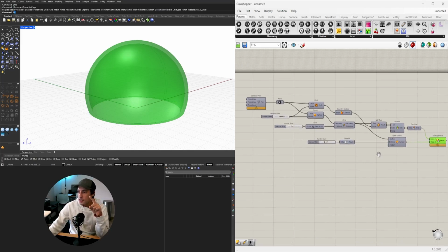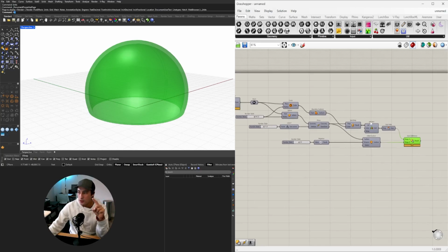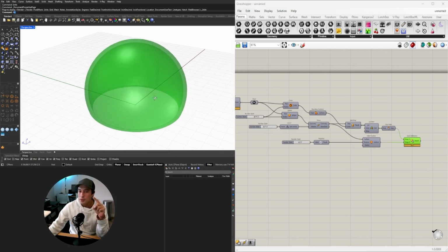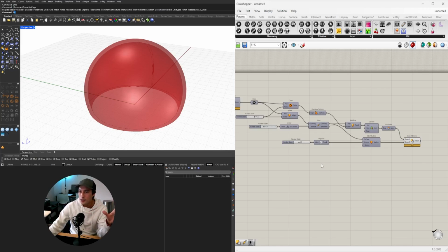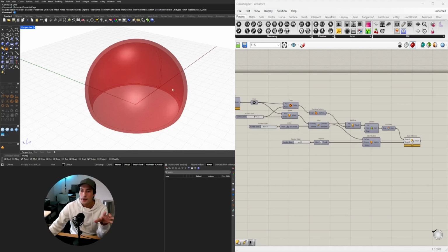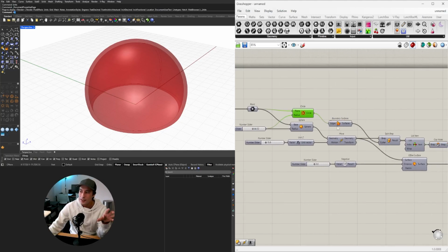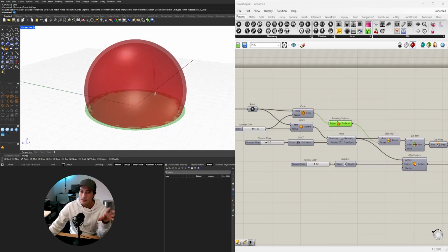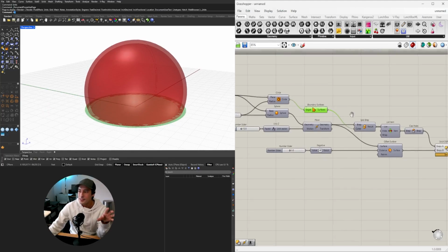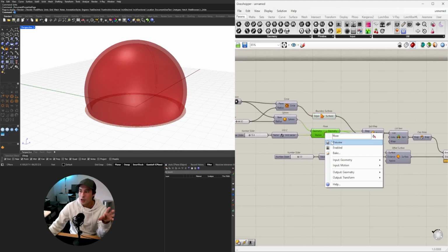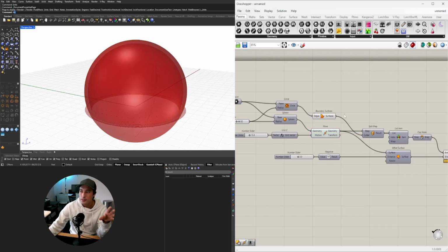All right, for this next part, for the door, we need to first figure out where the door is going to be located. And where the door is located, then we need to find the geometry that we could use to extract some kind of reference point to create that door. So when we look here, we want to create it obviously somewhere within the wall area, but what we need to bring back is that surface. And let's bring back the dome before it was cut. So we see that we have this dome, this surface. Now we need to know where they intersect.